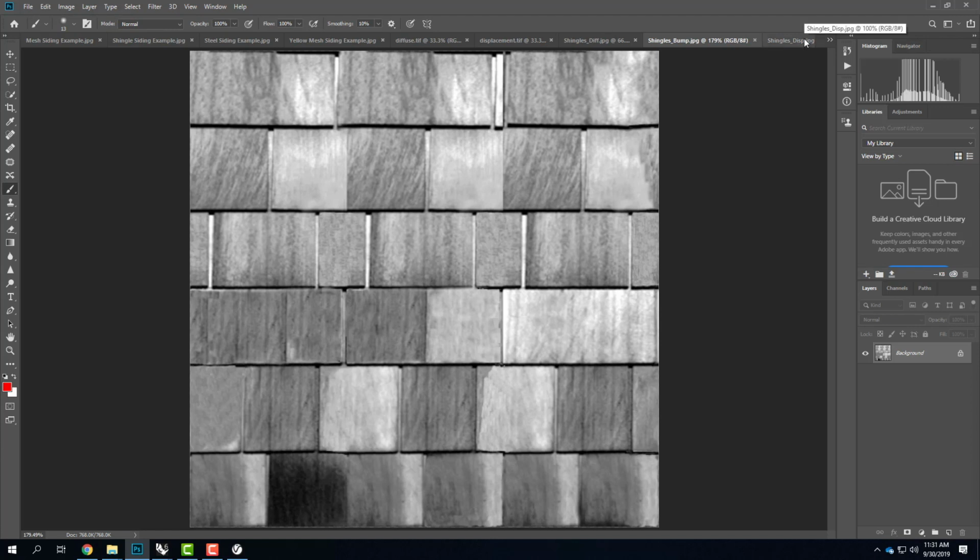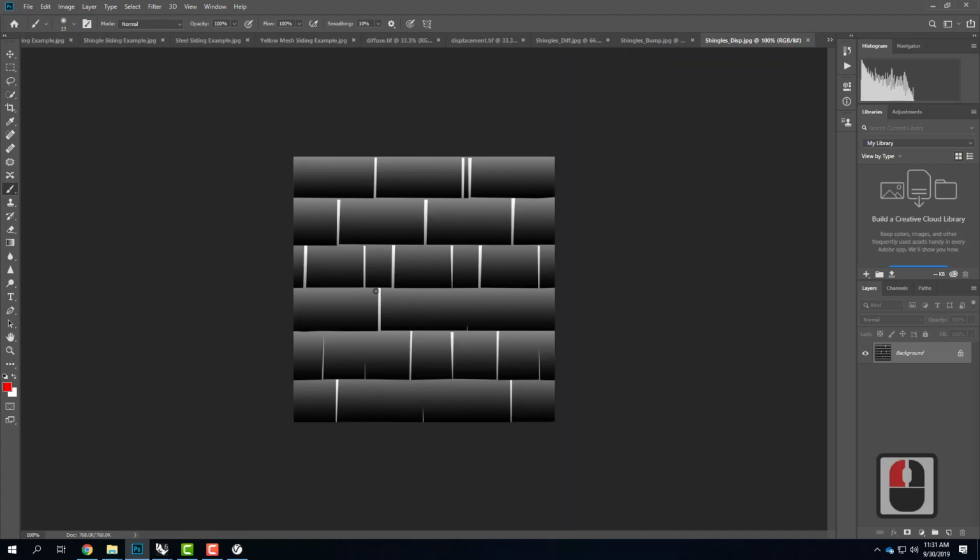The displacement map is different. So what the displacement map does is it says, at one end of the spectrum, in this case white, we're at 0 in our plane. As we go toward black, we're going to start to stick up a certain amount. So in this case, by going from a gradient from white here all the way up to black there, I'm creating a slope inside of the displacement. So it's going from 0, or flush with the surface, to sticking out by a certain amount.